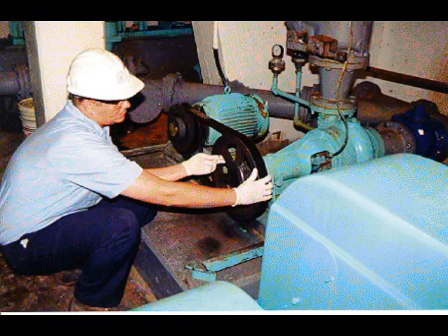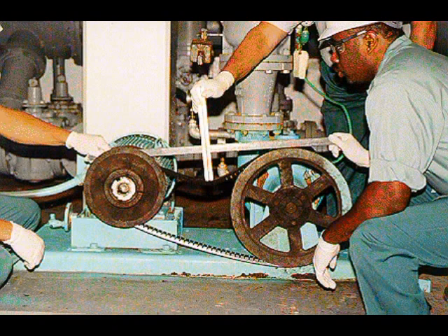The pump and motor shafts must be positioned so that the pulleys can be aligned with the belts in a straight line. The belt tension should be adjusted to the manufacturer's recommendation. Generally, belt tension on new belts will need to be rechecked after a brief initial run. Too much tension shortens belt life and increases stress and wear on the bearings. Too little tension causes loose belts and thus slippage, loss of power, shorter belt life, and wear of the belt sheaves.